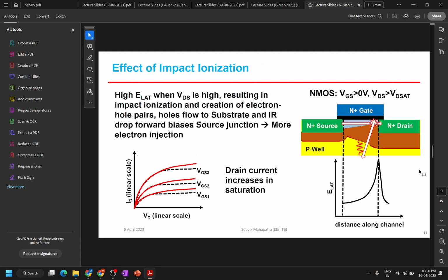The point you're saying basically comes within threshold voltage shifting. Your conduction is starting in the weak inversion state itself, so you can say that your threshold shifts to your weak inversion region.